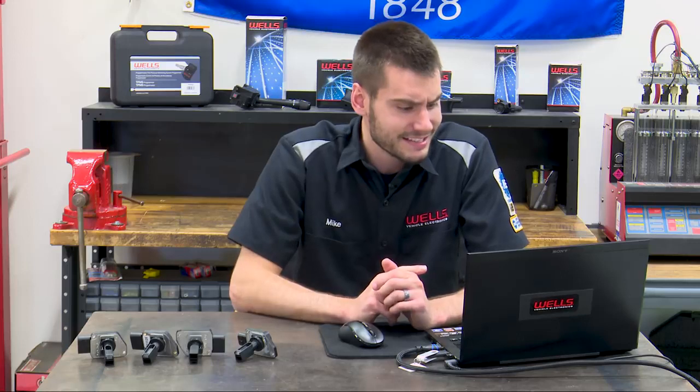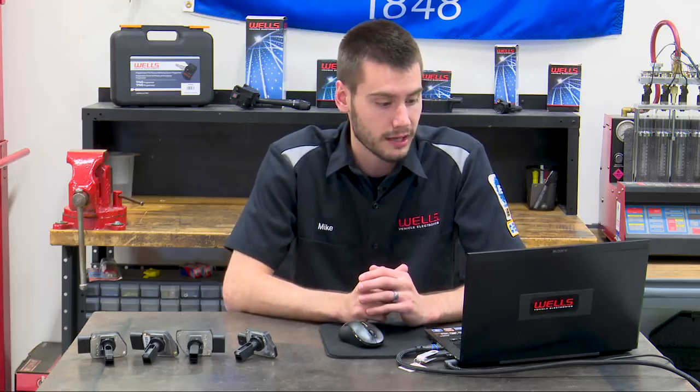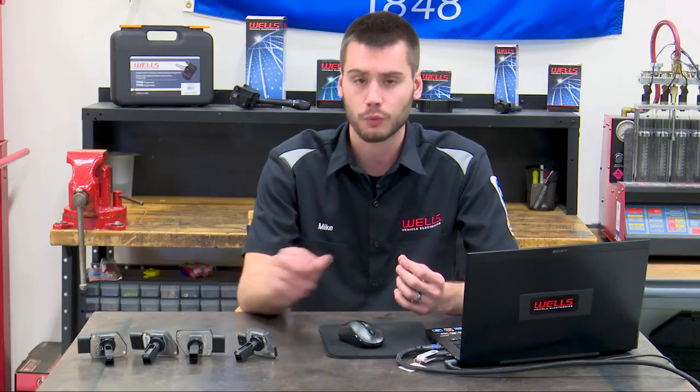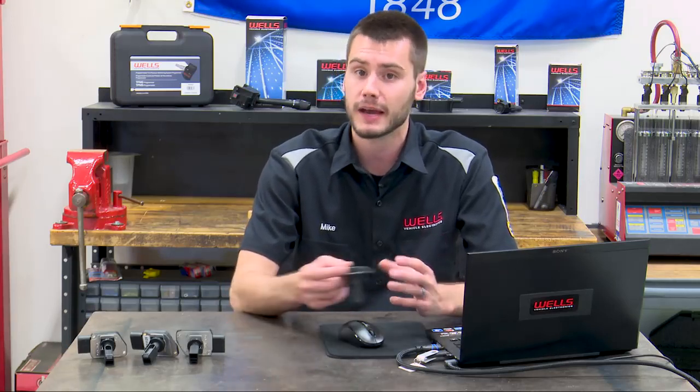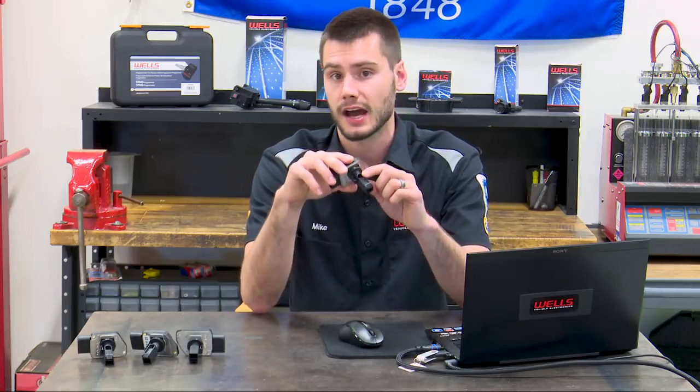New Level Auto came on. He said current can make you nuts. Only micro amp clamp is somewhat definitive. And this must have been the point where I was clamping the power wire going into the mass airflow to show you guys that the current draw would increase as we're trying to keep the sensor element inside hot.